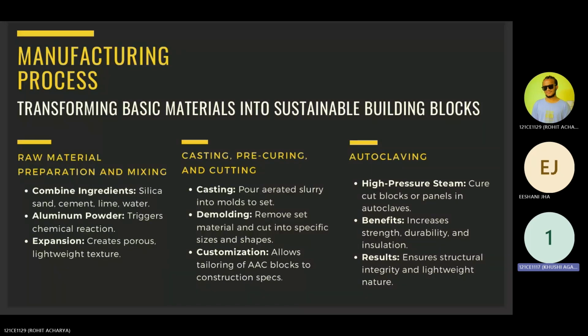to meet construction specifications. And finally comes autoclaving, wherein the cut blocks or panels undergo curing in autoclaves under high pressure steam. This process enhances strength, durability, and insulation properties of the concrete. It ensures both structural integrity and a lightweight nature of the final product.